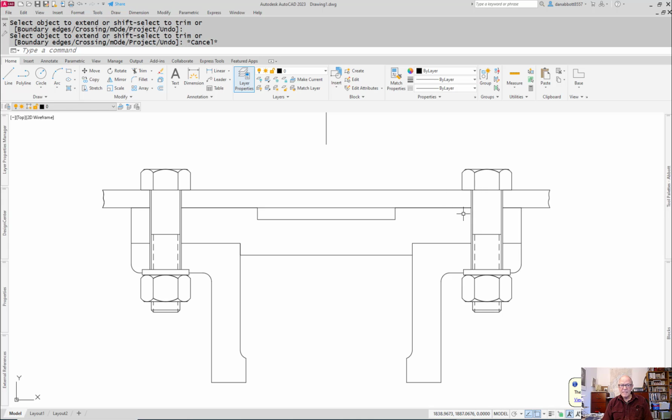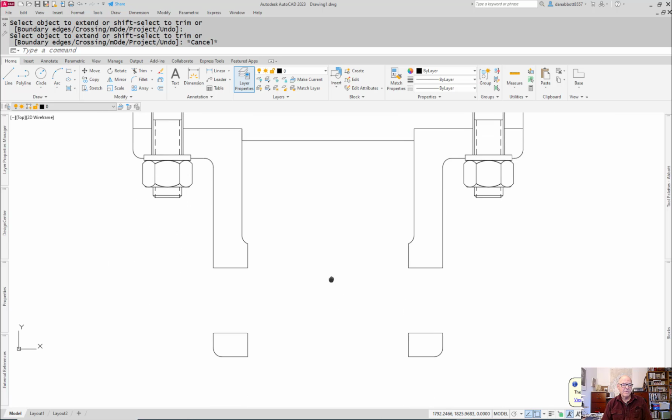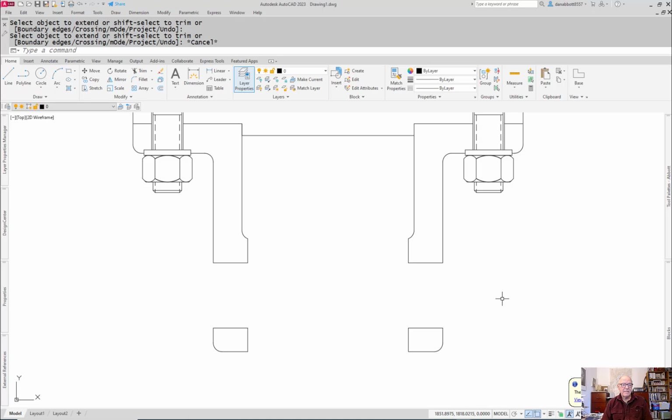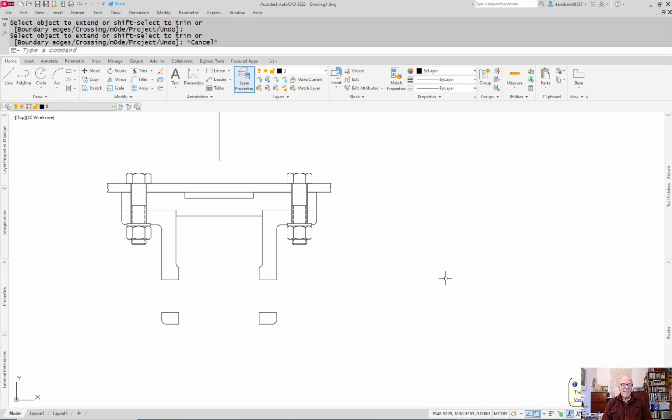Now you also have to put center lines in here, and you have to do all the things you've always done on drawings when you do your layers. But this again is an indication of how to deal with the geometry. Now what's going to go right in here is the axle. On this one I'm just going to draw the axle off to one side and then turn it into a block so that you can just set it in place and then use it to trim to, and it will not consist of a group of lines. Again, you could have made all these things blocks as well, but I think it makes more sense to make a block out of just the things that go on the outside. However you want to do it though, as long as when you're done your geometry is correct.